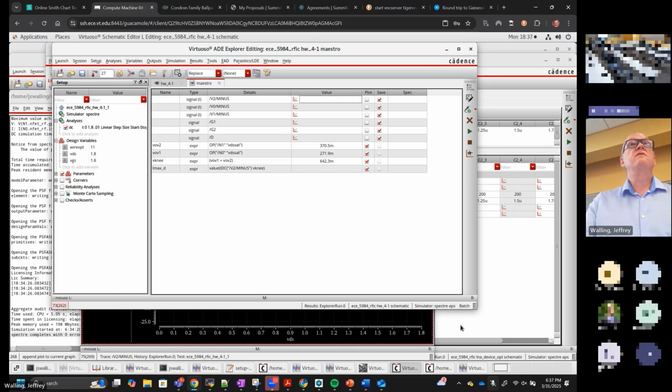All right. Yeah, so the overdrive voltage VOV is VGS minus VTH, right? Yes. So those devices also have different VGSs, right? Because both of their gates are at 1.8, but their sources are not both at 0. Yeah, so that's also contributing, in addition to what Sean said about the.